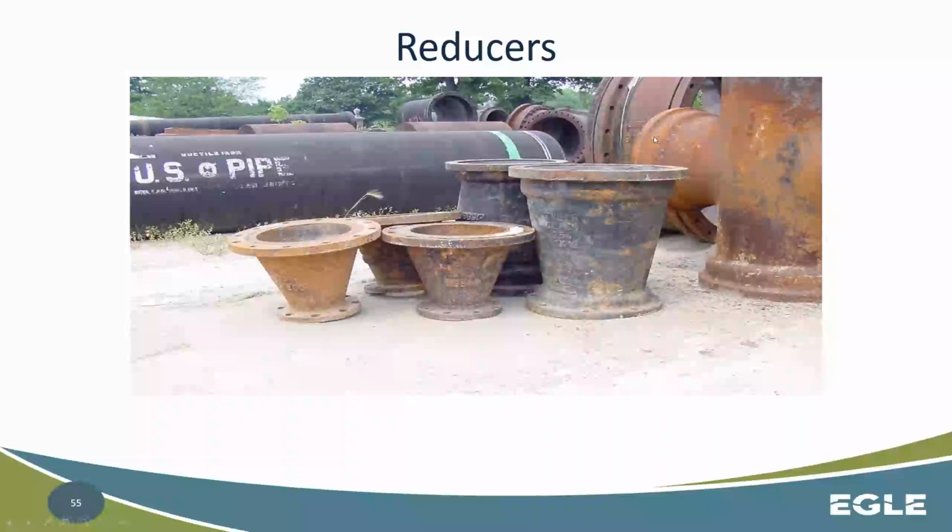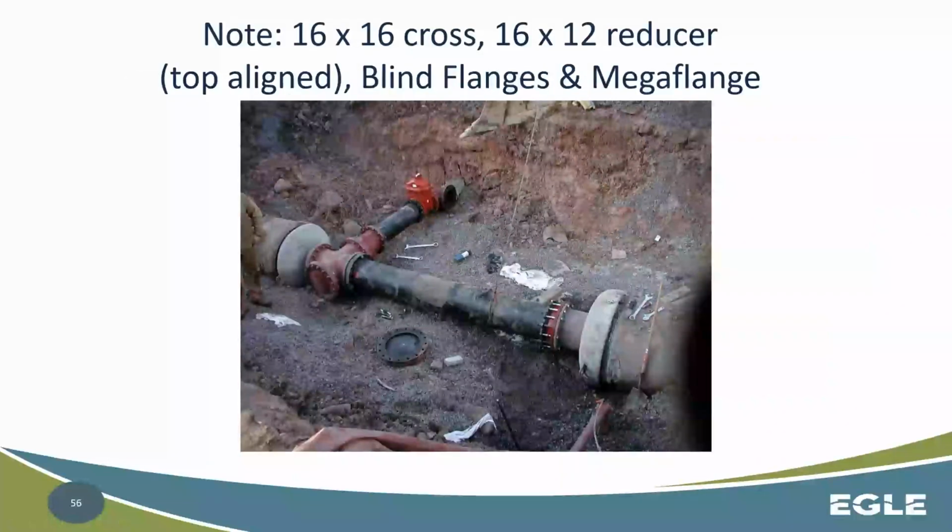Hard to tell exactly, but potentially here, I can't tell exactly if there's holes there, but that's a potential. And then these are just regular flange joints. There's no bell end. So that's just going to meet flat with another piece. And then that bolt, you can actually almost see the point where a gasket was originally. That flat gasket would have been sitting there. Okay. So this is just to give you real life examples of what's going on here.